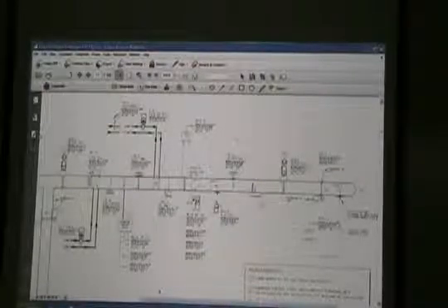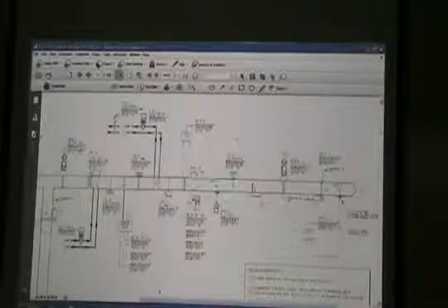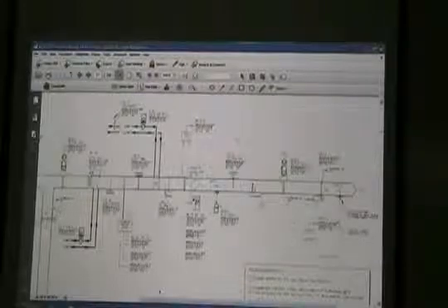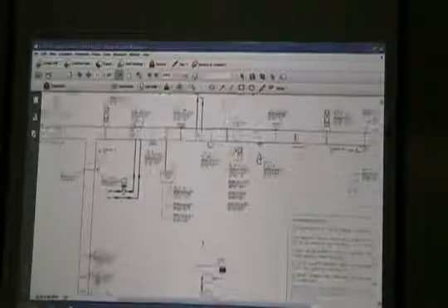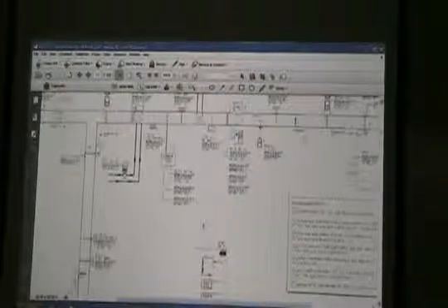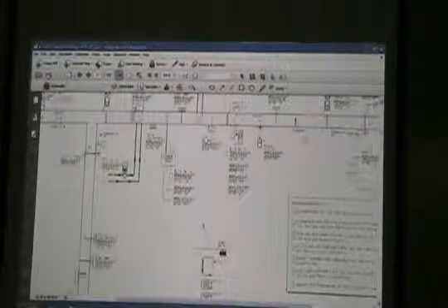Okay, humidifier. See the humidifier? Yeah, right there. Looks like an electric humidifier. Humidifier should be modulated to maintain return air humidity set point at 40%. So there's our humidity sensor in the return duct. That's the return air duct. We got a smoke detector, a humidity sensor, and a temperature sensor. So we're going to monitor that system. We're going to try to maintain 40% by enabling this humidifier.